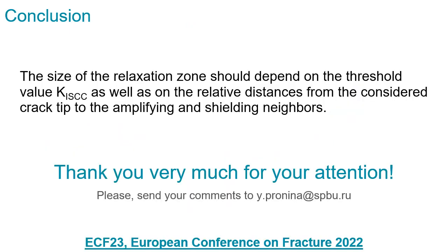Thus, we can conclude that introducing the relaxation zone of the same size for the cracks of the same length is not always reasonable. The size of the zone should depend on the threshold value K1 as well as on the relative distances from the considered crack tip to the amplifying and shielding neighbors.